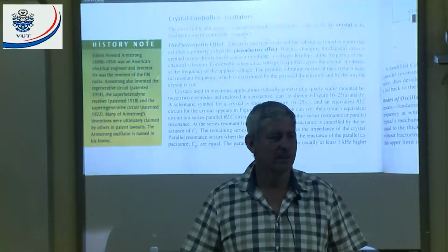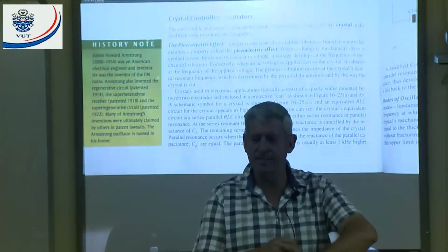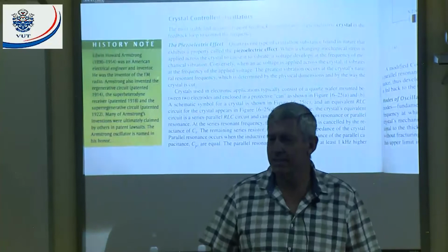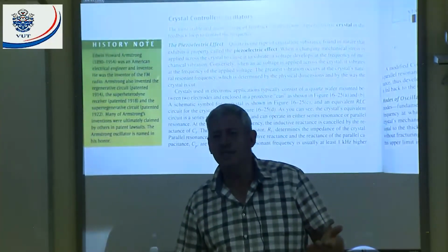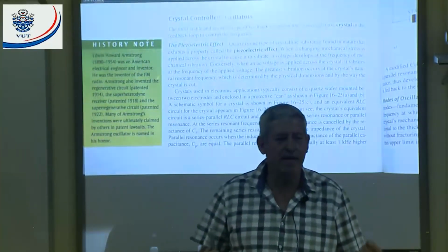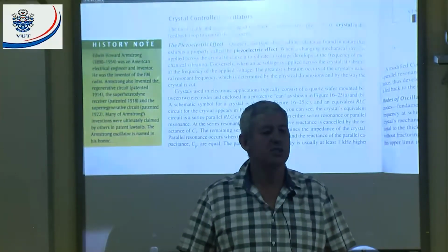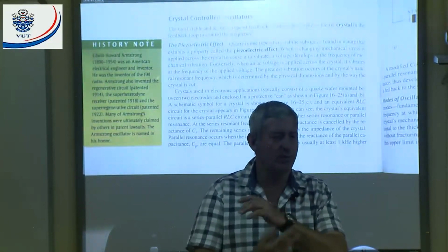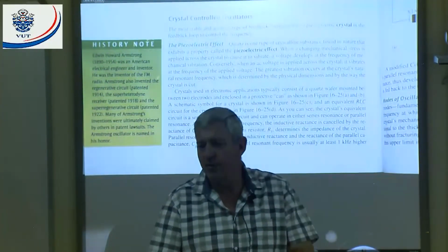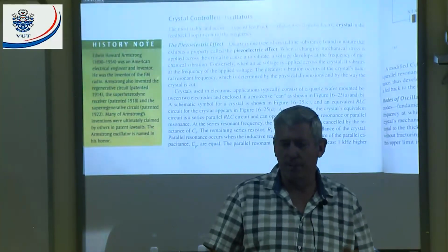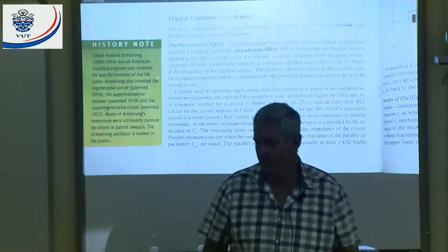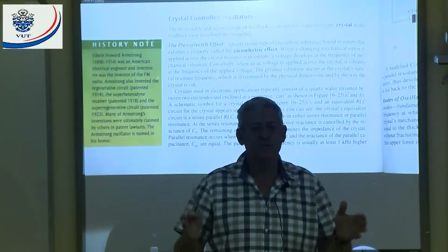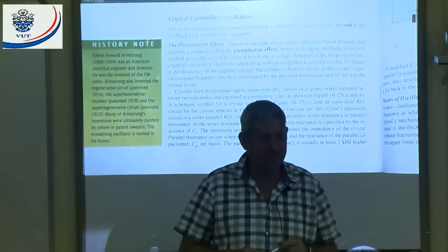There's a quartz crystal inside the watch, all right? And that is going to work as an oscillator. Now, why quartz as an oscillator? Because that will give me a quite accurate, stable frequency, especially if you keep the temperature constant. Normally your watch is on your body, and your body temperature will be fairly constant, and that's why that quartz crystal will give us quite an accurate frequency.